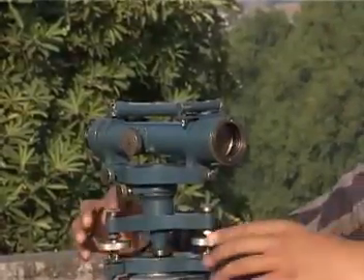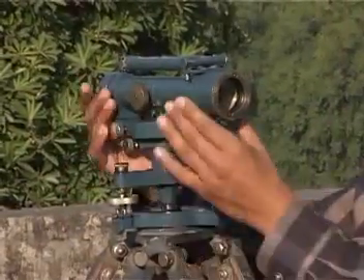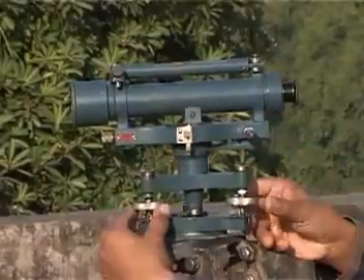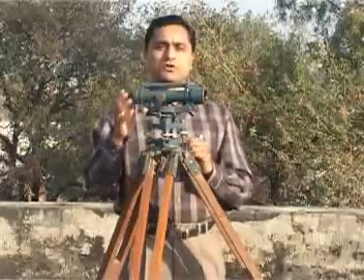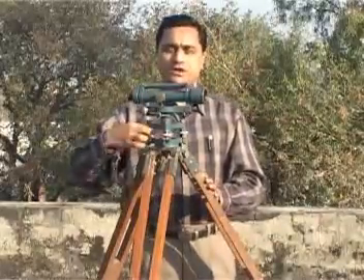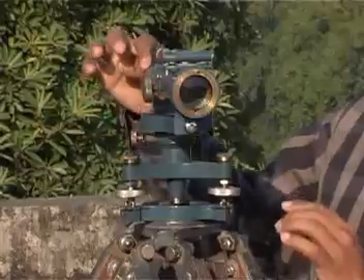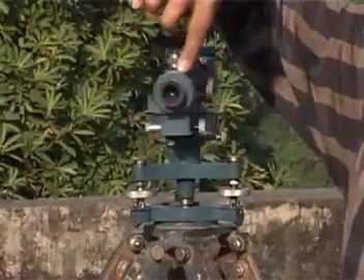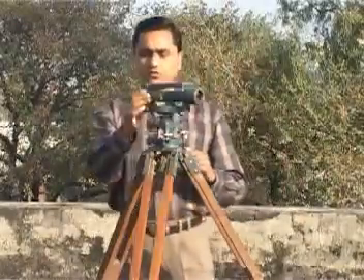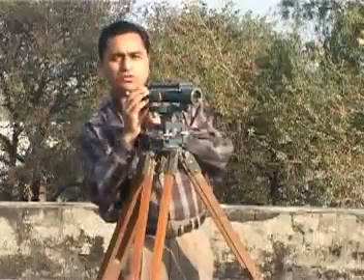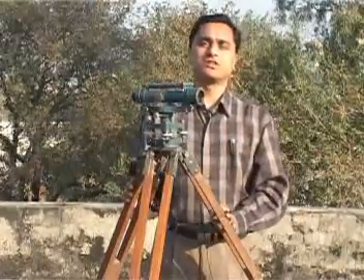Well, what we do is make use of the three screws here, as we did in the theodolite. Similarly, I will keep it parallel to two screws, for example these two, and I will level my bubble tube. Next, I will keep it perpendicular to that, and using the third one, I will again level it. By repeating this procedure, it will be leveled. The meaning is, now wherever I turn it, the line of sight will always remain horizontal. Having done that, we have the eyepiece here. Looking through this eyepiece, because there we have a cross wire, we can sight the staff and take the readings.